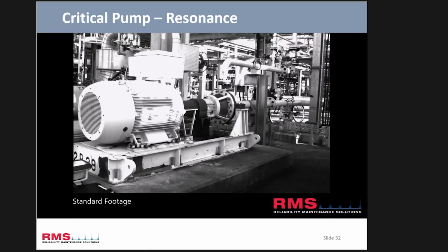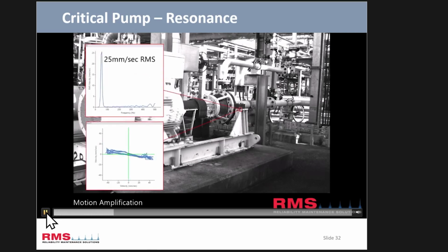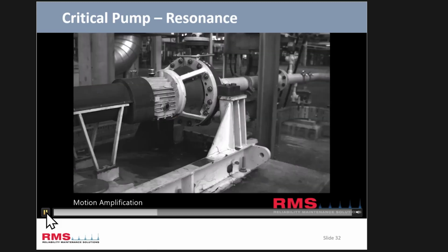This was a resonance issue which my colleague Dean was involved with. So again, a motor and a pump scenario, standard footage, and then he'll show you motion amplified, and you can see the back end of the pump there. There's a vibration measurement off the ROI off the pump in velocity with a little bit of an orbit plot there. So you can see how that structure's moving.